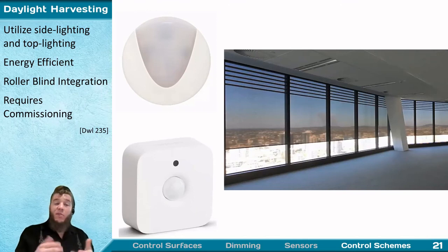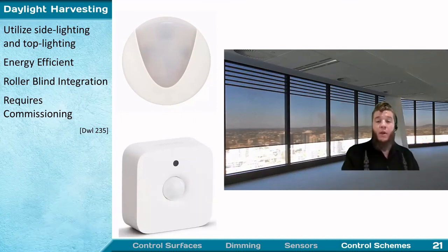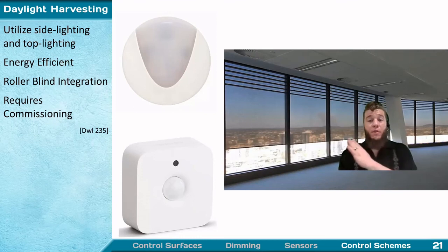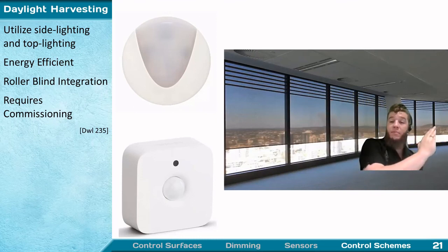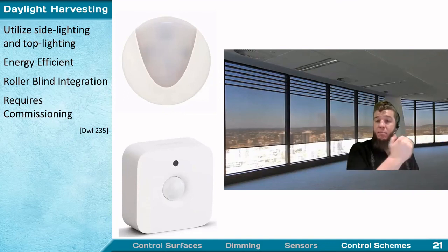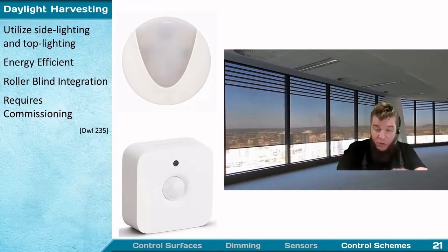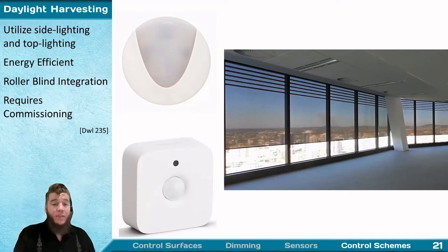And you're also going to need different zones of lights, either zones or individually controllable lights, to make use of this. Most likely, and this is a great example right here, you're going to turn off the zone of lights closest to the windows and leave the lights deeper inside the middle of the space on, so that the light level doesn't drop too much as you get away from those windows. Now, obviously, there's huge energy savings to be had here.